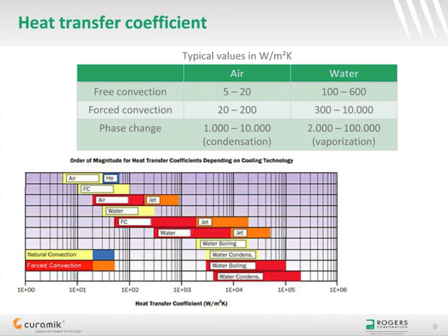Liquid cooling, for instance with water, outperforms air cooling by having heat transfer coefficients several orders of magnitude higher, thus enabling much higher power densities and more compact solutions. However, liquid cooling comes with its own risks and potential problems, such as leakage, corrosion, and condensation. Therefore, liquid cooling is reserved for applications involving power densities that are too high for safe dissipation by air cooling. But liquid cooling has to be preferred to air cooling for applications where compact and lightweight solutions are required.